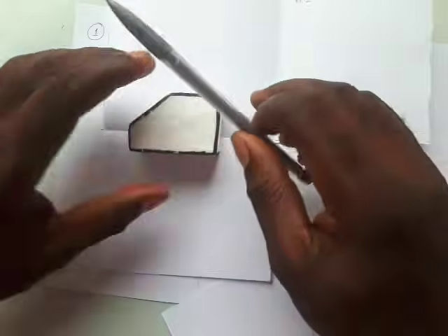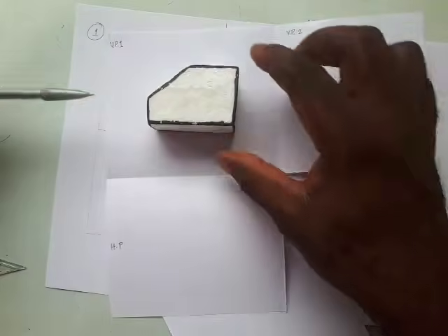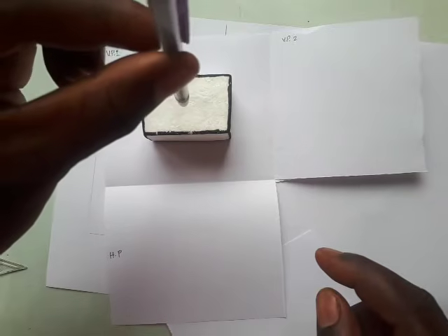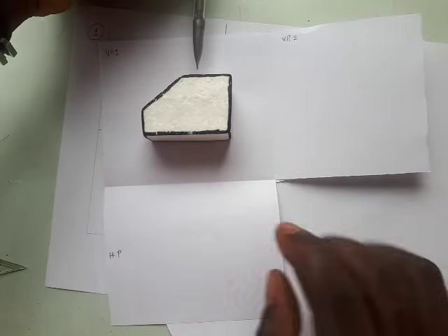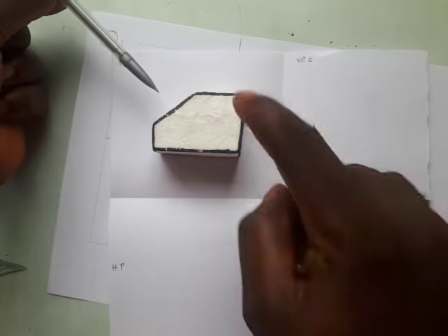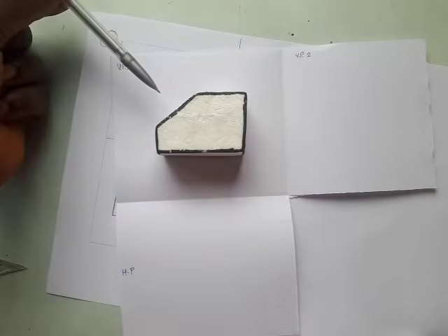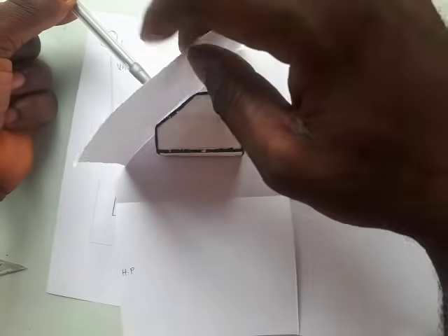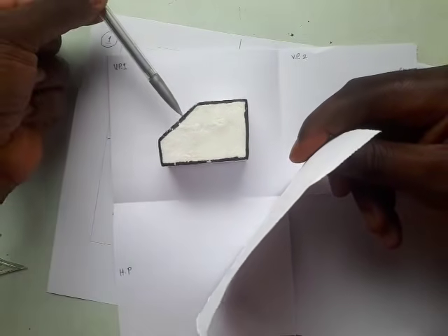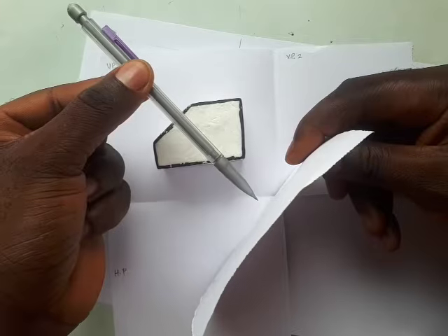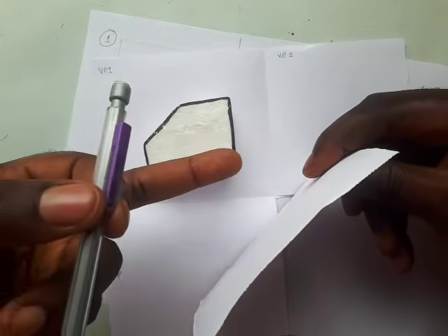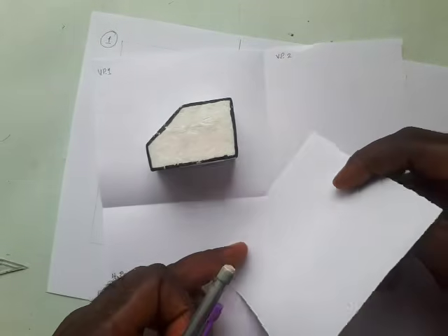Now, if I'm not viewing this object perpendicularly, but at an angle other than 90 degrees, so if I'm viewing at this angle, I need to create a plane for it that is perpendicular to it, put it at the back, and draw whatever I see on this plane. That makes it an auxiliary view. So whatever you draw here becomes an auxiliary projection. The plane, if I flatten it, is going to be in this form.